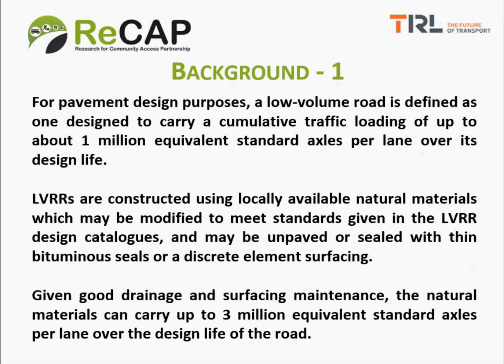Low volume roads are constructed usually using locally available natural materials, which may be modified to meet standards given in the low volume road design catalogues. In other words, we're using materials that are not the strongest available, but we are using ones that are locally available and therefore hopefully cheaper. They don't have to be hauled a long distance and so on.